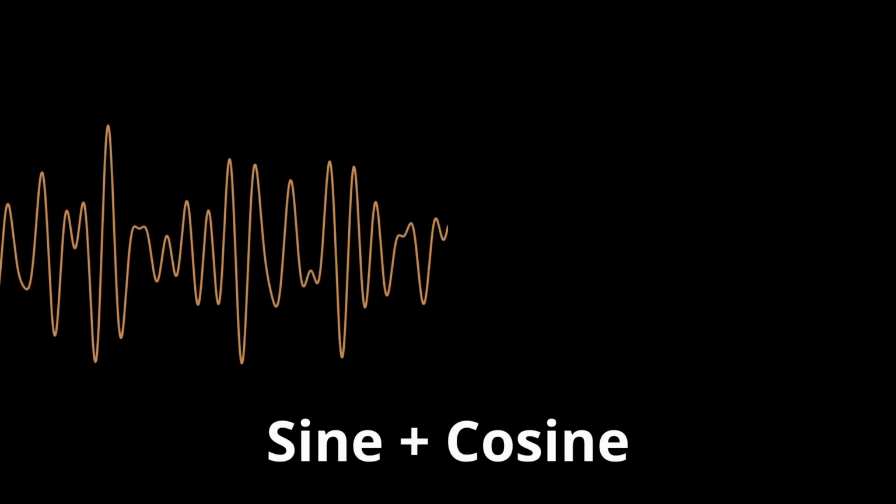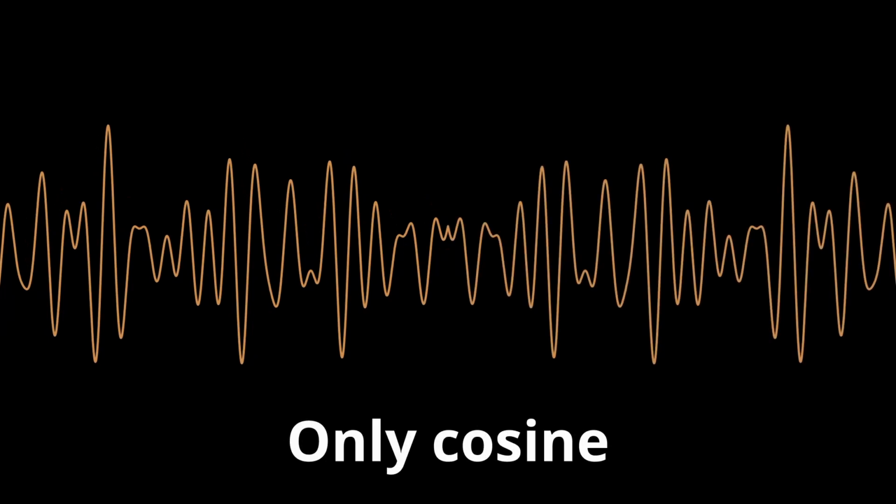We mirror the signal. Let's say we start with this wave. Instead of wrapping it around a normal Fourier transform, we reflect it. This mirrored signal is perfectly symmetric. Because of this, sine components are automatically 0. Only cosine components remain. Now, when we measure the frequencies, we only need cosines, and that measurement is the DCT.